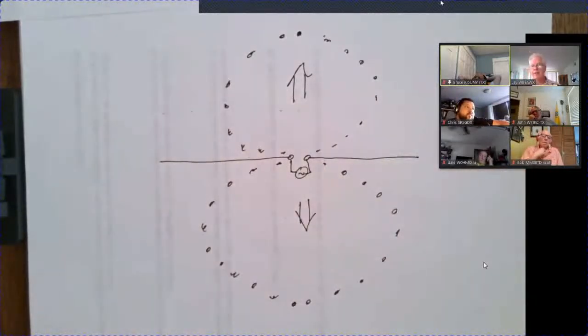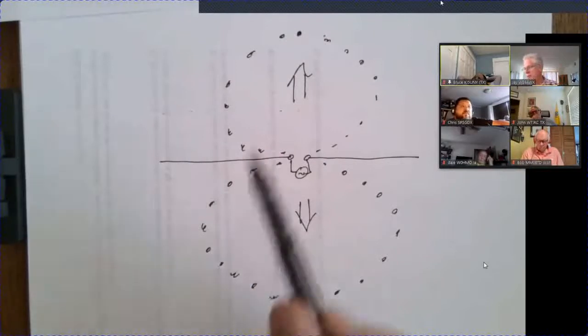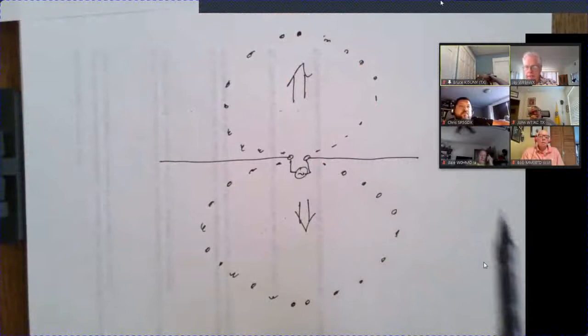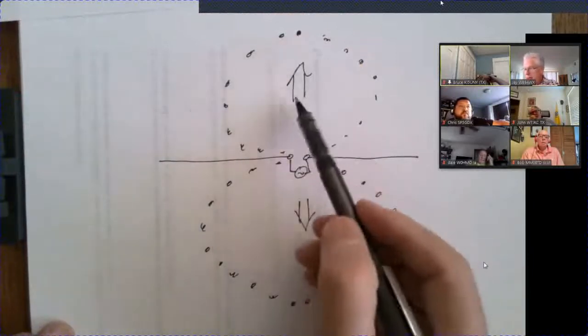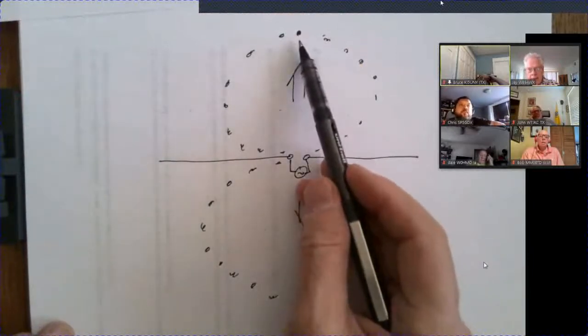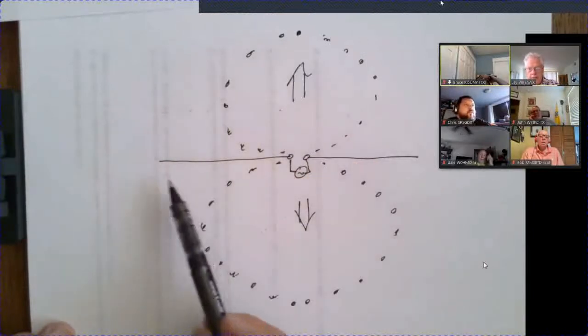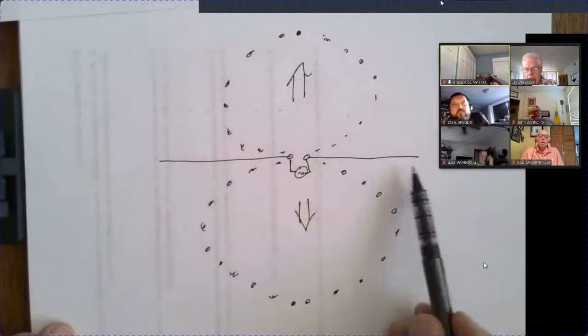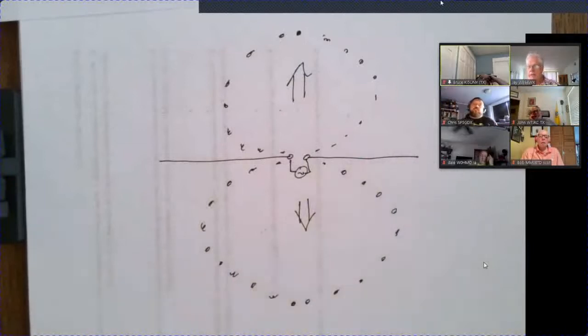So this is why sometimes if you are targeting a particular area, you may have to move your wire antenna around or rotate it or whatever you have to do. But this has to do with how we add those up. But again, here's the kicker though. The amount of power coming out of here is proportional to the currents flowing here and the lengths of the wire. So again, if you have little current, they don't add up very much.